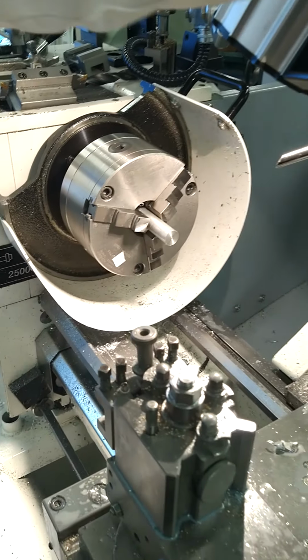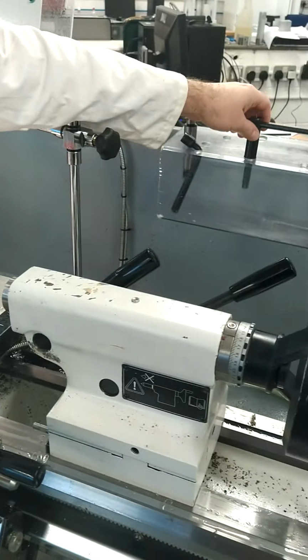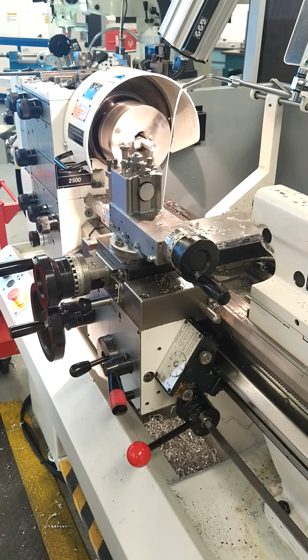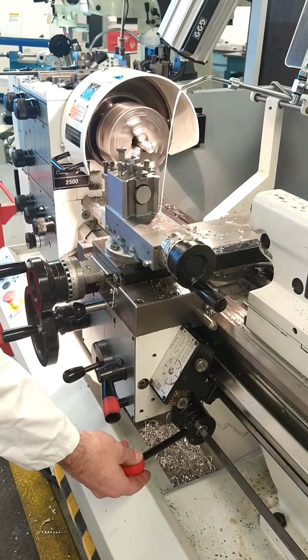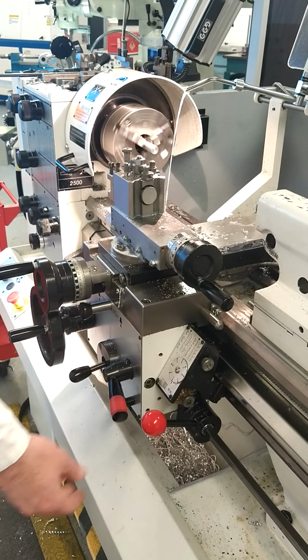So I'm putting my chuck key back into its holder. And now to start the machine for the very first time, making sure we can operate it safely. We're away from it with no cutting tool in place. We're just going to start and stop the machine for the very first time. So we're pulling this lever out and down to start, and that's travelling clockwise. The material is turning at 260 RPM. To stop the machine safely, lift it out and up, and it stops stationary.